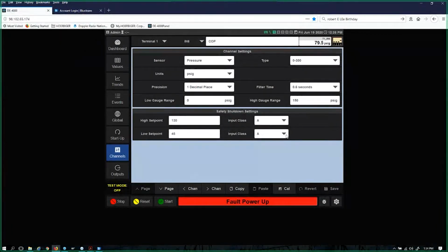And what we've done in the past with a lot of systems is we simply push the reset button while it's running to reactivate those Class C timers. Well, what that reset button does is it also reactivates all the B timers. So knowing that, now also think about what we just did under the global section for the system, where we selected when our B timers and C timers start counting down. They start counting down the minute this system sees RPM, 100 RPM in our case.